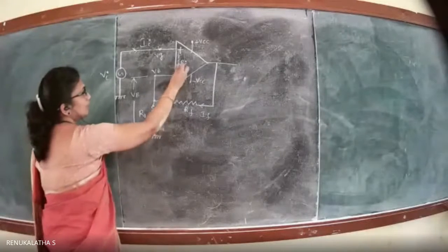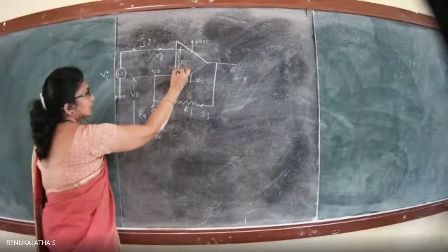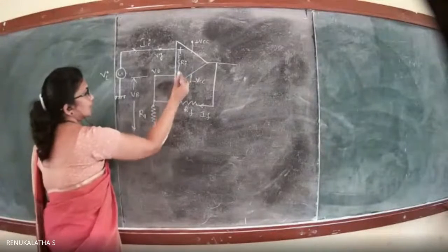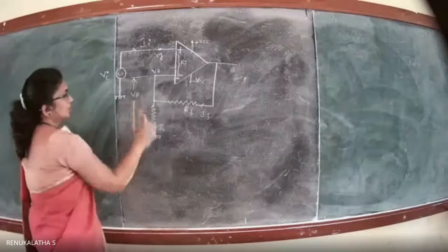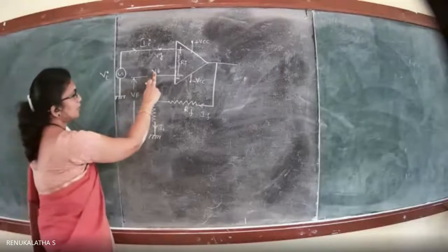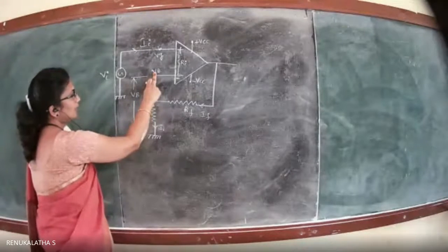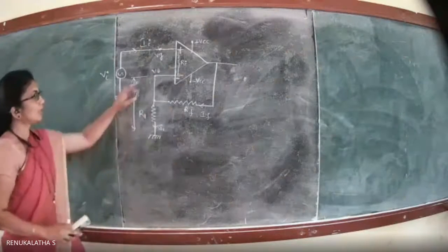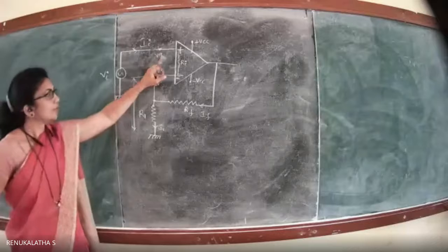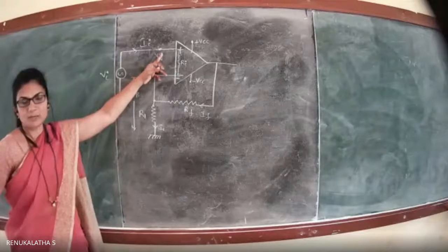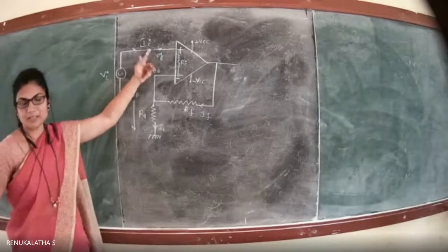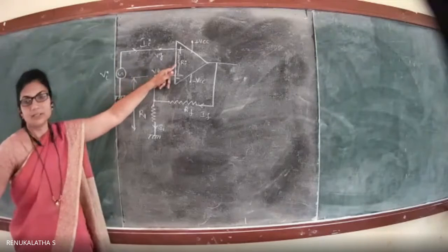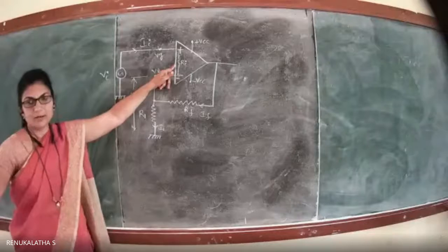So this is the resistance that is existing, and let us take, because we have to measure the voltage, VB is always measured with respect to ground. Earlier, in the previous circuit, the other terminal was grounded. So directly you could guess the potential at the other end, because already one terminal was grounded, as the resistance between the two input terminals is very high.